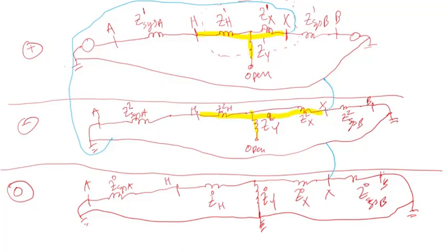So what would flow here is 3I0. So that's the total zero sequence current. So it's 3 times, because really what would flow here is 3I0, and we know I0 will be the same as I1, the same as I2. So the zero sequence current is the same as the positive sequence current, the same as the negative sequence current.